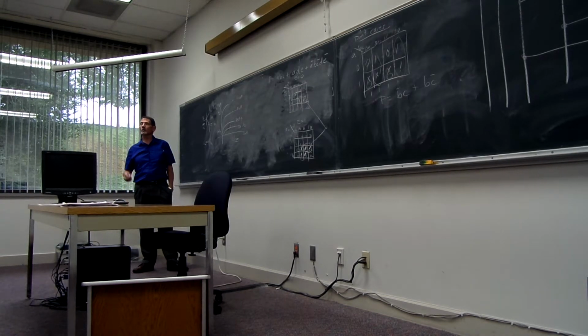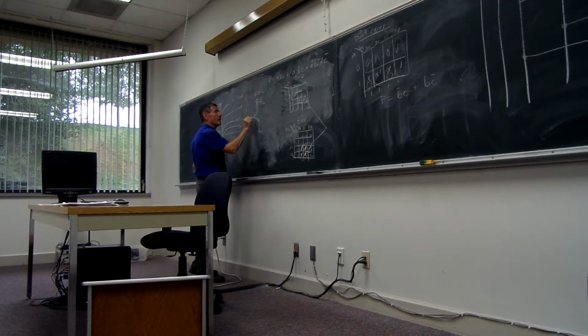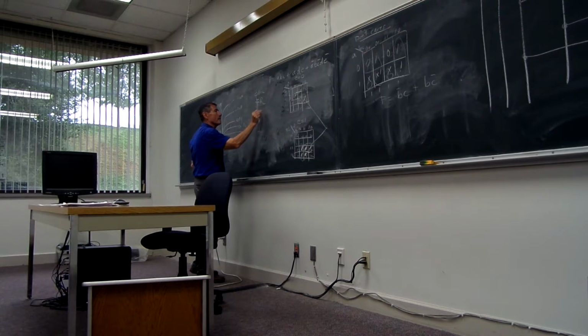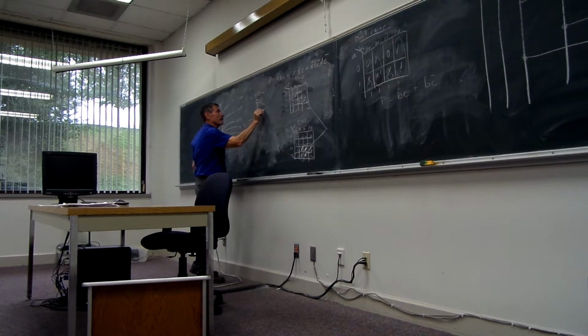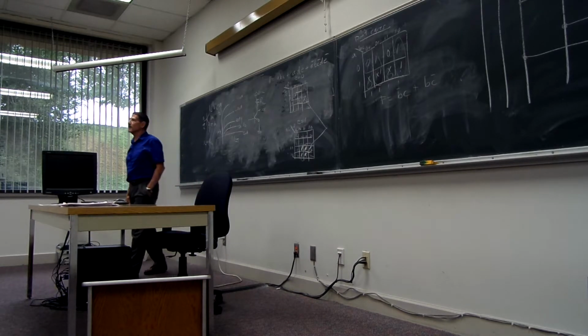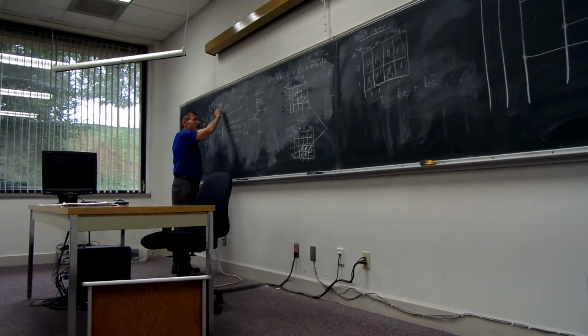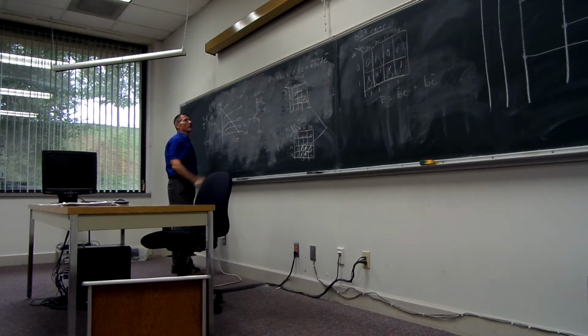So we have what are called load lines. If I were to put this transistor into this circuit here, we can draw a load line such that we could figure out the maximum collector-to-emitter voltage we'd ever have, and the maximum collector current.